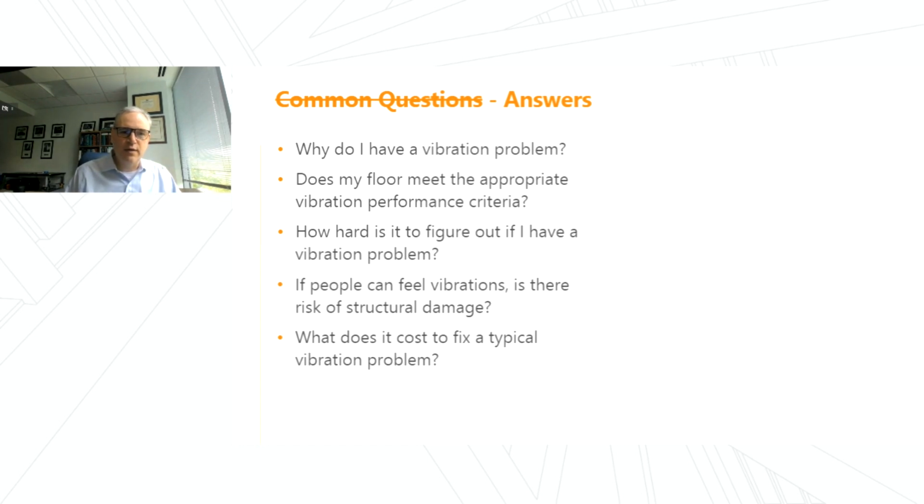So why do I have a vibration problem? A lot of times we have that question. Flexible floors is a very common situation. In many cases, we get human perception, and as we've talked about, different people walk differently. Through an adaptive reuse, owners don't appreciate that the structure fundamentally has changed. In many cases now we're seeing, in addition to the existing flexible floor, high-density cube spaces. So we have more people moving and more people perceiving those vibrations.